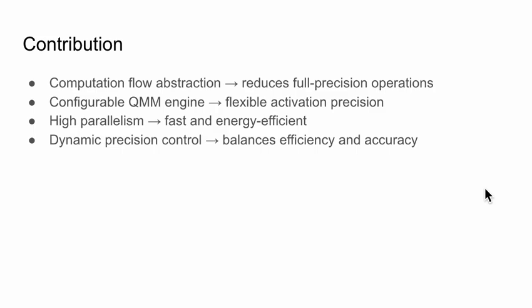In conclusion, BETA demonstrates how binary transformers can be deployed efficiently on edge devices, supporting multi-precision operation with high parallelism, achieving impressive energy efficiency and throughput compared to prior FPGA, CPU, and GPU solutions.